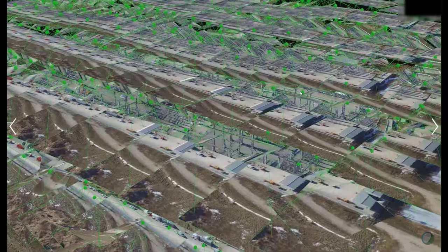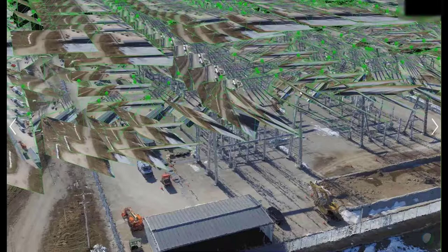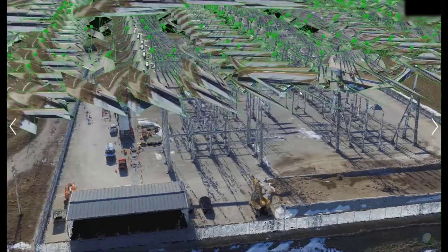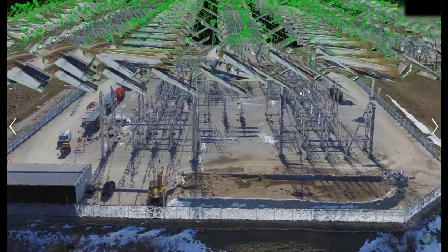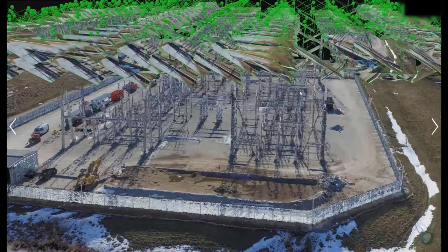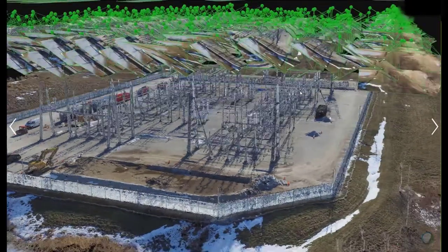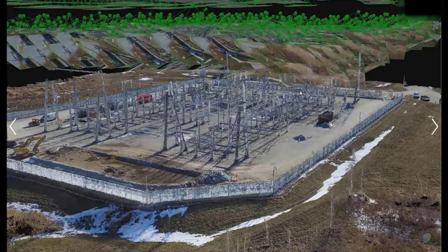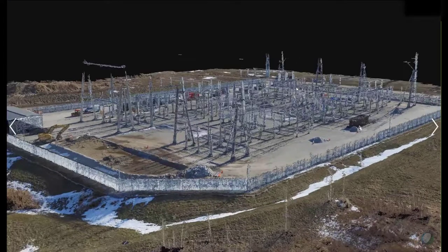And then we use a technique called structure from motion, which is an image processing technique. And finding like features in those images, we can actually digitally reconstruct a 3D model of that site, which you'll see here in just a second. So the photographs of the drone are above, and then there's a digital recreation. This is what is called a point cloud. It's exactly what it sounds like. It's a big cloud of points. Every point has a position and a color. And so that is the output of this drone scan.